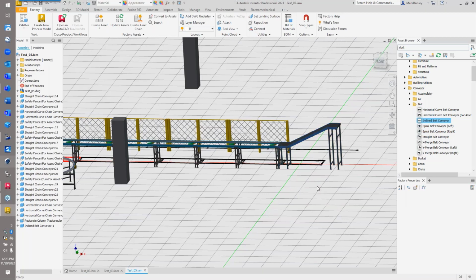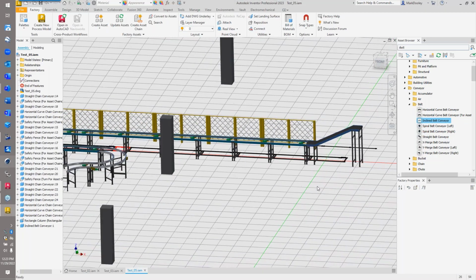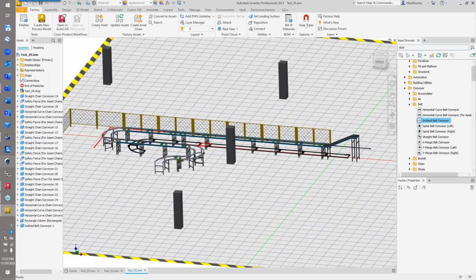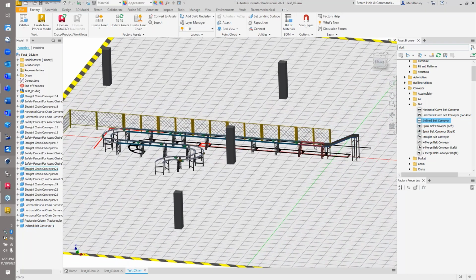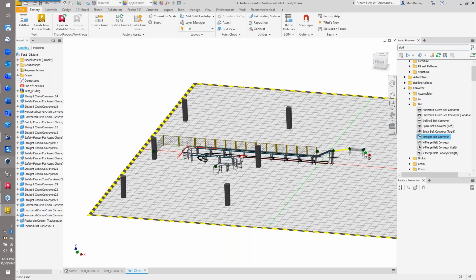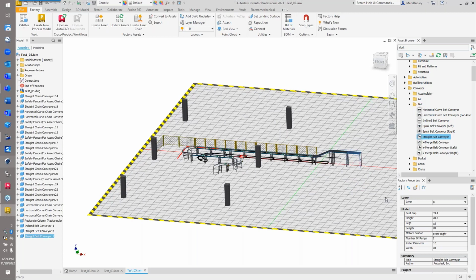And so it doesn't have to be the same type. So any of these components that we attach together, in this case, we've got a belt conveyor and a chain conveyor, and we put those together and we update one, the height on the others update as well. If we come in now and we say we want to add a straight component, and we just start adding in a couple of the straight components here, they're coming in, they're picking up the same 78-inch height here.